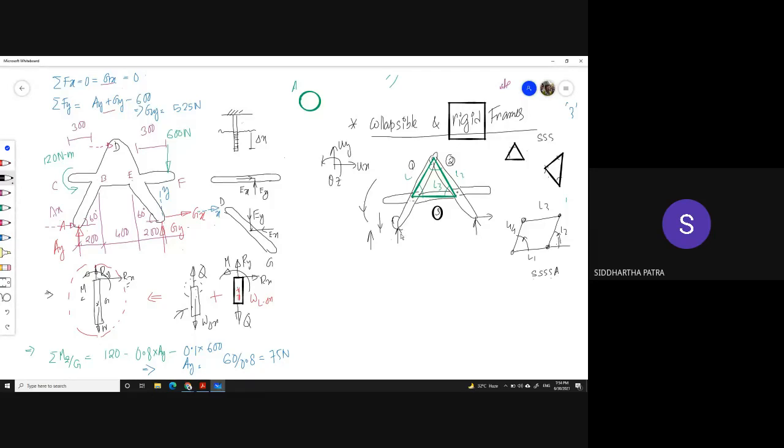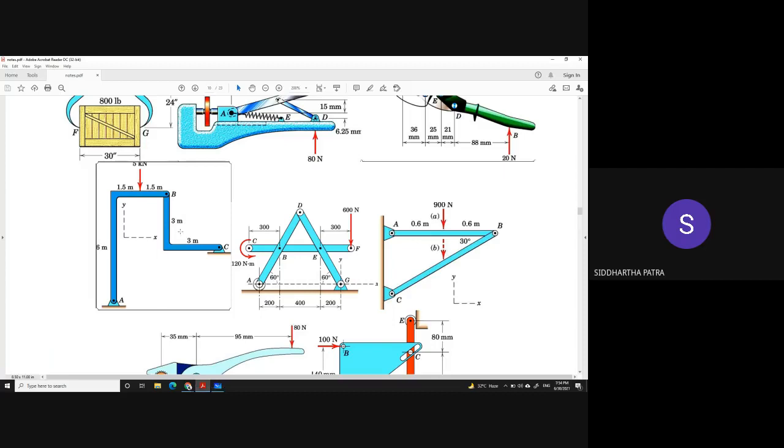Okay, the third independent motion. That's why you need only three constraints from the ground to make the rigid frame optimally constrained. Now, with all those examples involving a 2-force member and a 3-force member, and even these two, a 2-force member that is BC and a 3-force member that is AB, the 2-force member, let's say CB in case A, and the 3-force member AB.